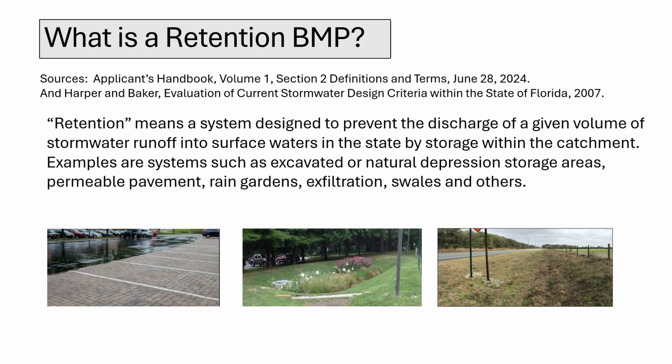The volume of water collected and held within these retention areas is referred to as the treatment volume. While this volume is critical, it's important to understand that it's rarely large enough to contain all the runoff from every single storm event. Therefore, a key aspect of designing and evaluating retention BMPs is calculating the percentage of the annual runoff that can be effectively retained. This retained volume is also known as the capture volume. Understanding and accurately calculating the storage volume is essential for determining just how much of the annual runoff a basin can prevent from reaching surface waters.